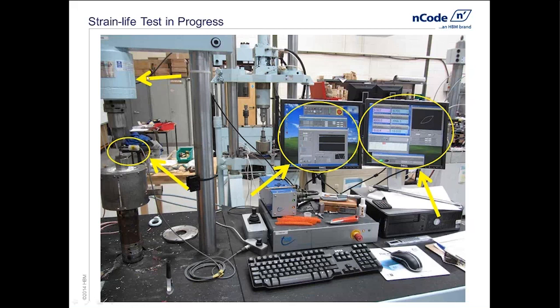That is measuring the load that's transferred to our specimen from the test rig. Our specimen is down here, gripped between these two grips, and attached to it is an extensometer. Basically, it is an instrument that's clamped onto the specimen at the gauge length, measuring the strains on that specimen as I load it.